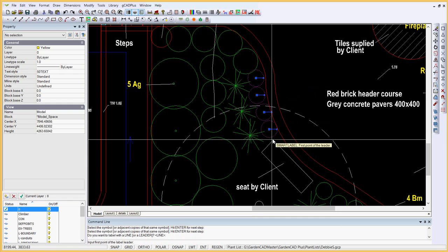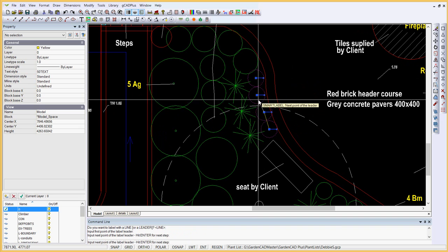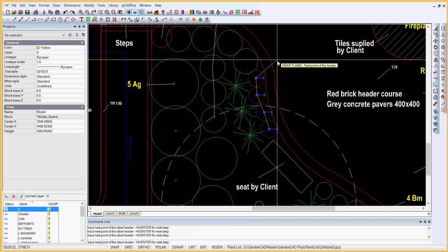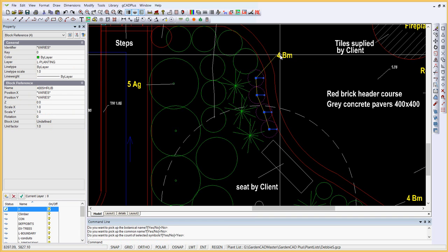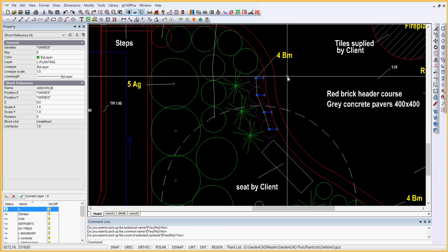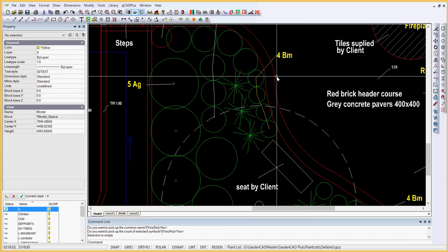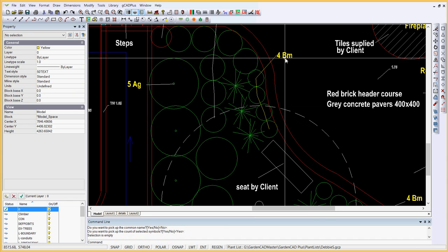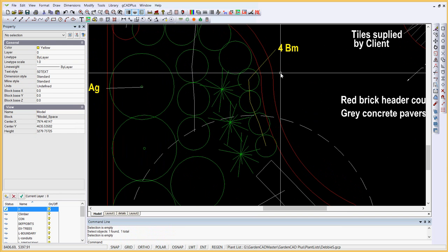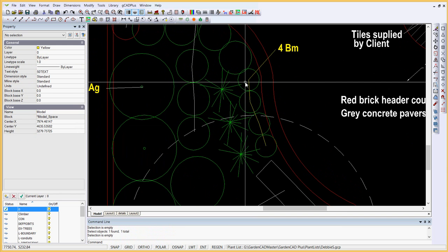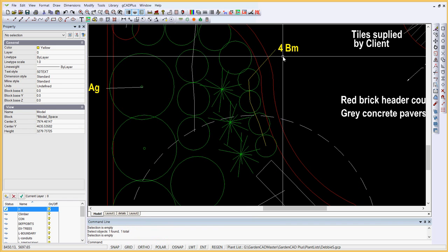We'll stick to line, and we just snap from midpoint to midpoint, come out here, indicate, hit enter, enter, enter, enter, enter, enter. Remember, it's the prompts from the previous occasion, unselect all. So now we've got a label. We can adjust a little bit if we need to, but we have a label running and locating and doing the count for us at the same time.